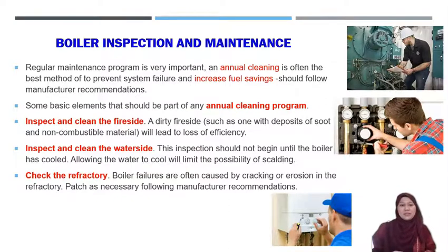Okay, boiler maintenance and inspection. The keywords here are inspect, check, clean, replace. All of this is under maintenance. Annual cleaning is compulsory. Then inspect and clean the fire side, which is the furnace side, for any deposit of soot when you provide the heat. You also clean and inspect the water side, where you store the water.